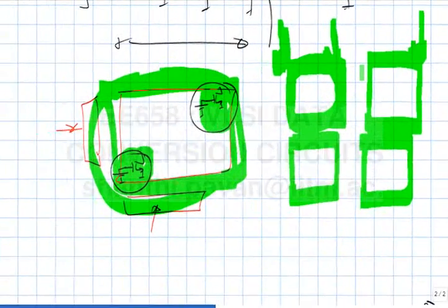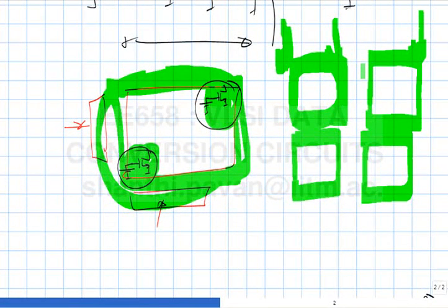There is a whole bunch of theory about how you can randomly assign current sources at different places and average out this whole thing. I am not going to get into the details, but all that I want to emphasize is that there is a problem with gradients of oxide thickness and threshold across the current source array, and one way of fixing the problem to some degree is to split this into 4 smaller DACs. Since each of these DACs is smaller, it will occupy a smaller amount of space. You put 4 together and then add them up, okay?